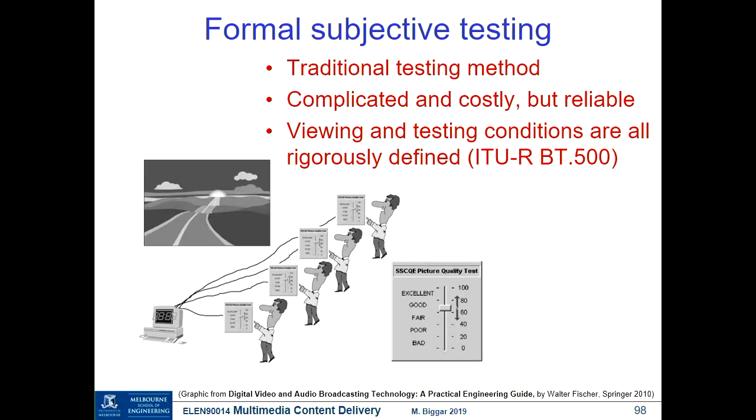And from what you understand about predictive coding and motion compensation, you would realise that as you fade to black, the next frame you're about to encode is very similar to the one before, but it will give a poor match to a motion compensation check, to motion estimation. And so it was just an omission. It's just hard to predict these things in advance.